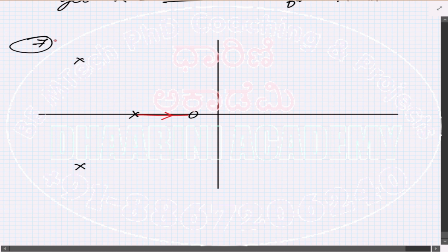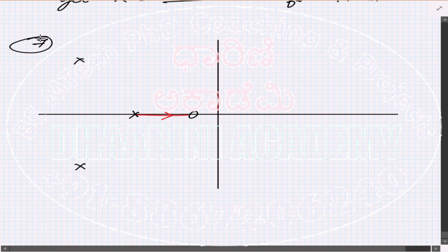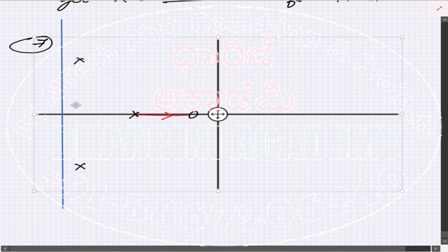So I understand that I will definitely draw asymptotes. Somewhat randomly I'll draw some asymptotes now. Let's say the asymptotes that I'm going to get are like this. Maybe it's 90 degrees. Asymptote in the sense that, by the help of these curves, it's going to reach infinity. So this is the point at which the asymptotes start. So sigma a, and phi a is 90 and 270.